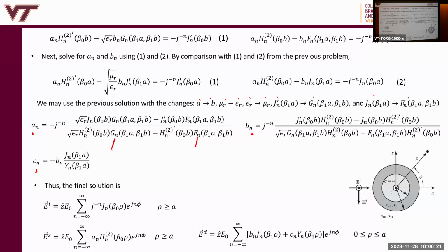Yeah, so you're talking about solving for a Green's function of this structure, right? For a Green's function, you have to place a source somewhere, like a delta function, and solve for the scattered field everywhere. Yeah, it's possible for sure. You can make a Green's function for these in terms of modal expansions and matching coefficients. You can do that. Okay, good.